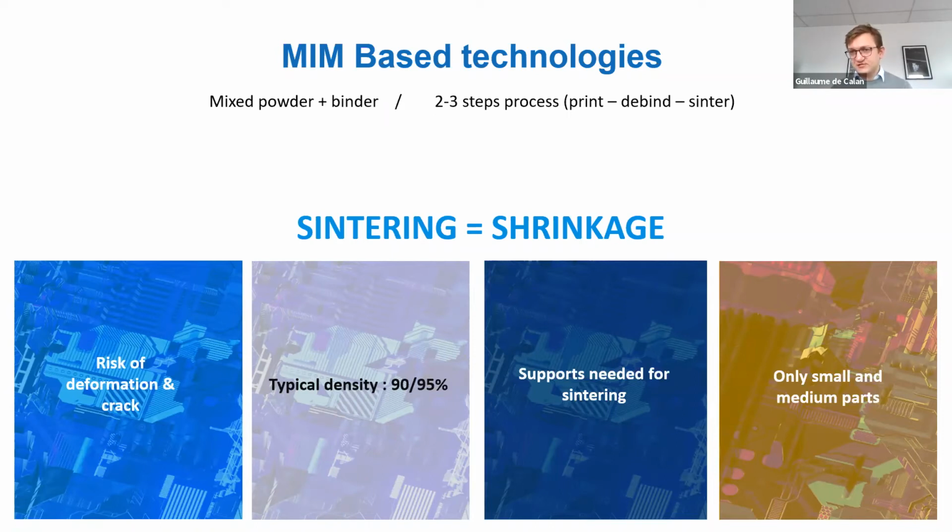That's a common trait for all of these technologies, which really means this is great. I mean, that kind of technologies are really interesting. Of course, we play in that market, so we feel it's an amazing technology, but it really has some limitation, and these limitations are physical limitation linked to debinding and sintering. So you can't go around them by using another MIM technology. All of the MIM technologies will have that same common point.